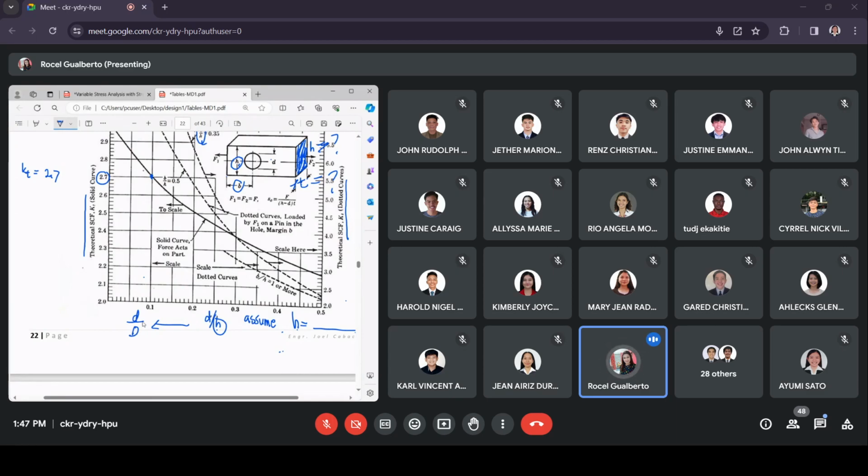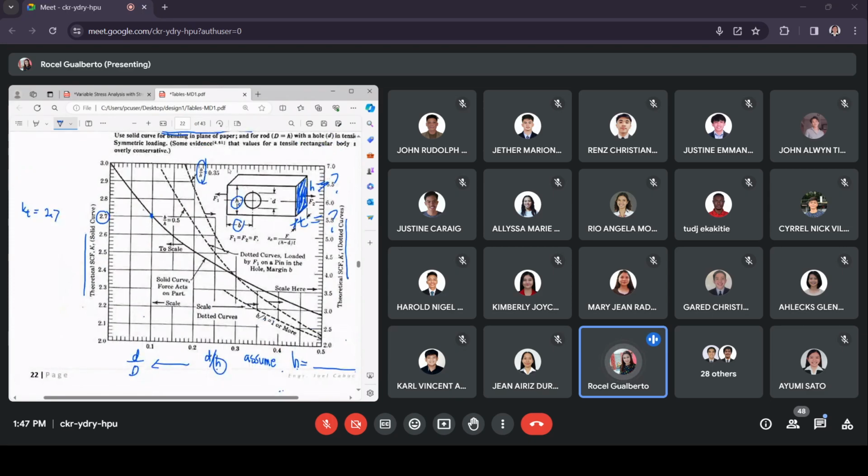So this is the new ratio if you transform this to a shaft with a central hole. What else? What about this B over H? Instead of B over H, you make it now B over D, since our H would be equivalent to the diameter. This B value here would of course be given.